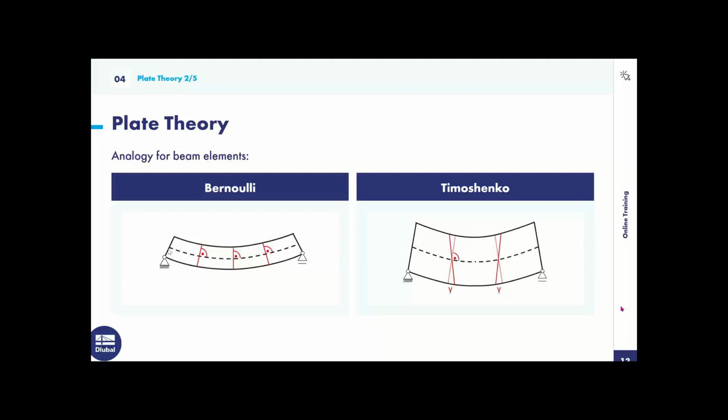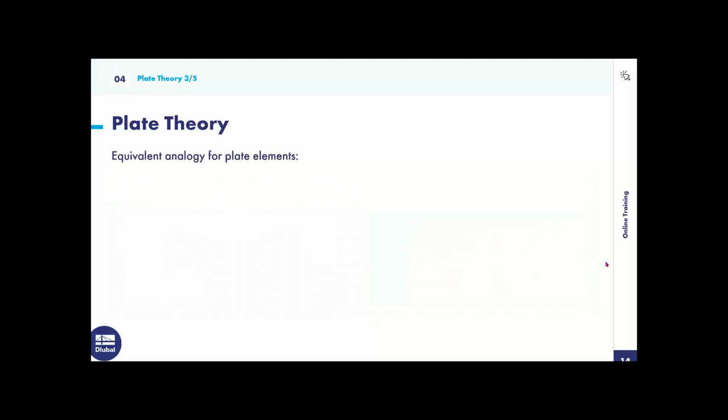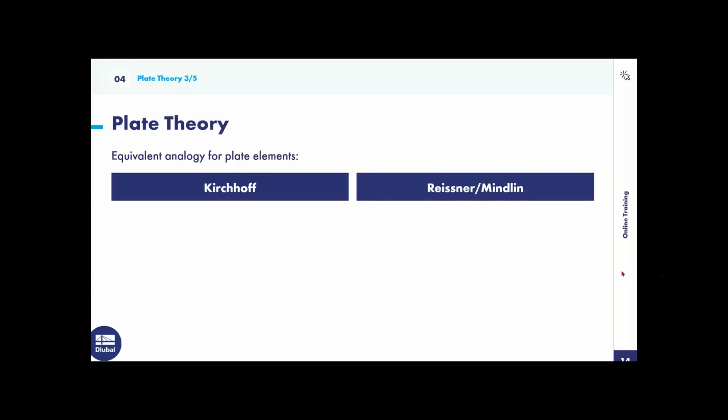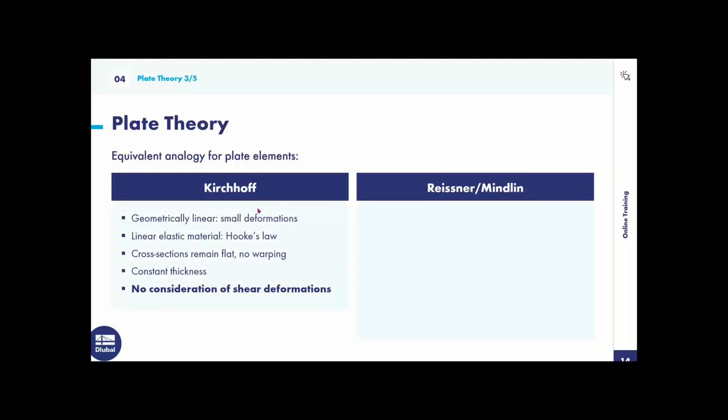So these two theories we can apply to plate theories. For an equivalent analogy for plate elements, we have the Kirchhoff theory and the Reissner-Mindlin theory. Again, the assumptions for Kirchhoff are similar to Bernoulli's theory, but for plates, and the similar theory to Timoshenko is the Reissner-Mindlin.